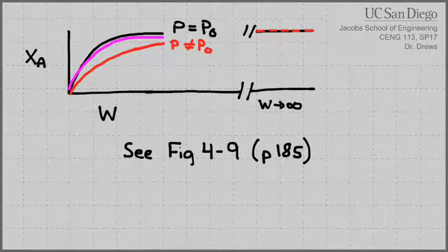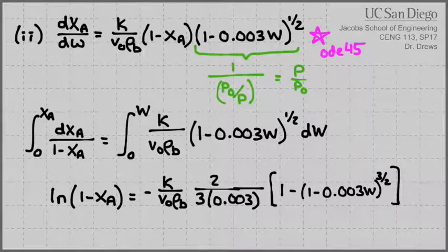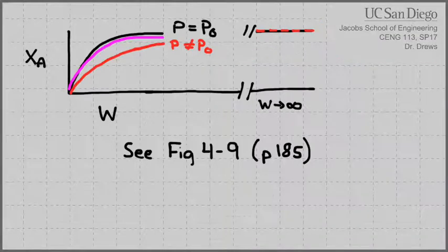This is going to be one of the effects that you'll have to explore both on some of the homeworks, but also in the project. Because in the project, you're going to need that full Ergun equation to represent the pressure drop, and that pressure drop can become pretty significant in the project statements. The derivation there wasn't particularly complex. All we did was start off with the material balance and plug in our expression for P. The problem was designed such that we could actually integrate that thing analytically. You'll see the same qualitative results in these kinds of plots, regardless of whether the system has to be solved in something like ODE45, or you get lucky and can solve it by hand. The same thing's going to happen.